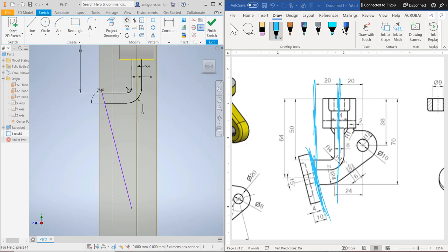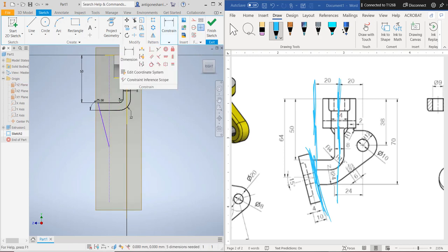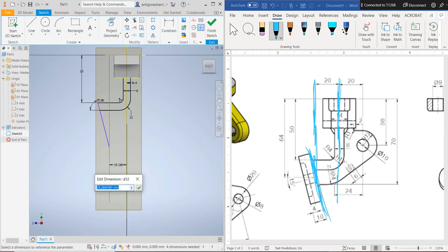But what I'm going to do right now, though, I am going to ask you to trim this. Why? Because it's still not constrained. What am I missing? The dimension. Don't forget the dimension. Once you drop that in, 20. That looks great. Now what?